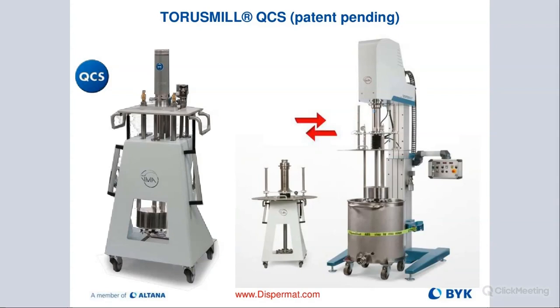You can see here with that cart, that's what's used to do that transfer from a dissolver over to the mill head. We just put the cart in there, lower the shaft, put that motor flange on top, loosen the clamping ring, turn the assembly 180 degrees, and then you're just moving on to your milling. That change takes about 5 or 6 minutes. We did it this morning on a customer trial. So it's really efficient.